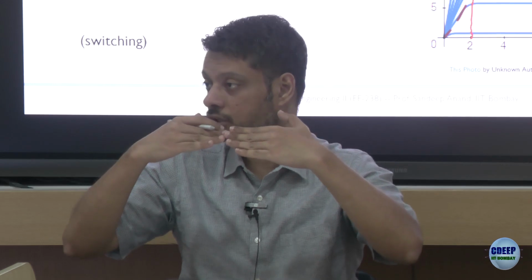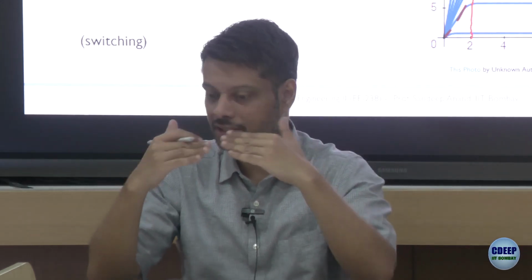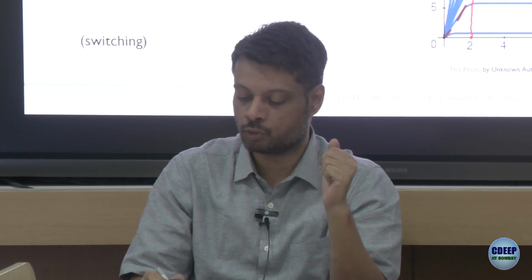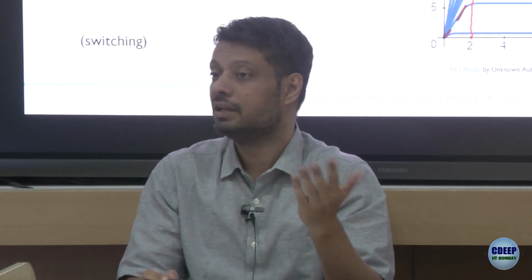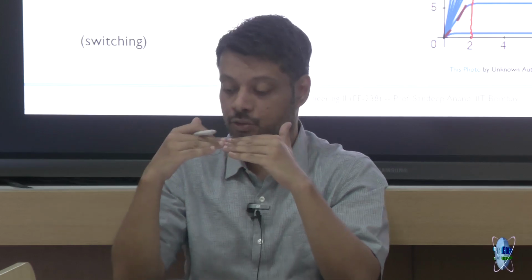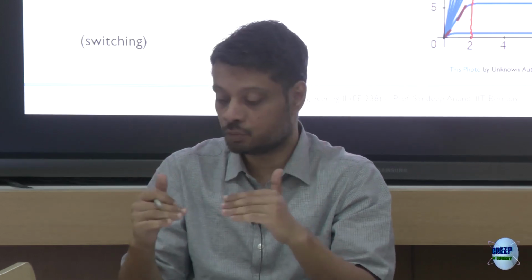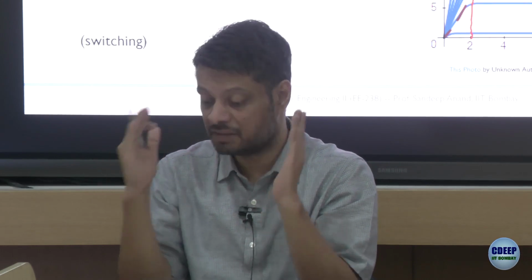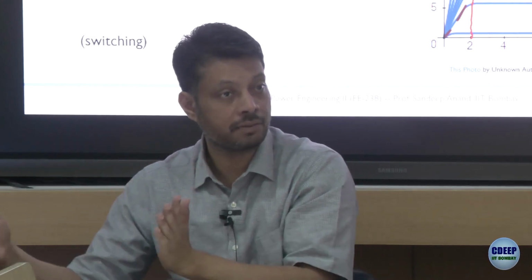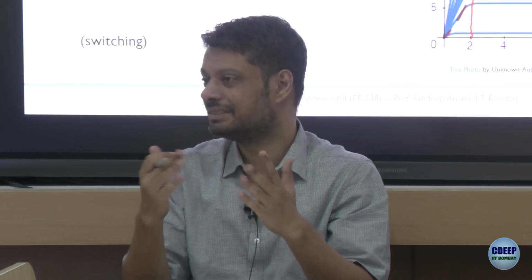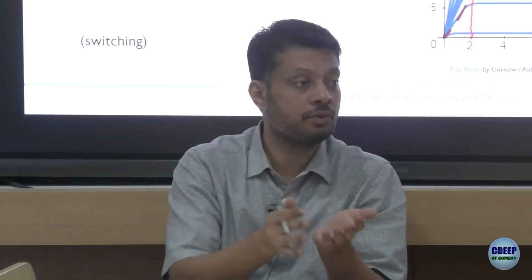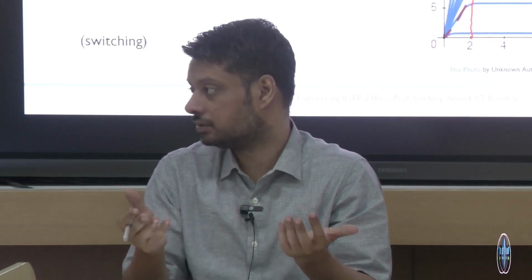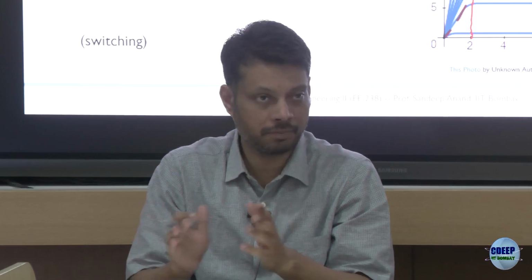It acts as a short circuit, not a perfect one, but a very good short circuit, because the voltage drop is only 2 volt even while pushing a very large current of 25 ampere. When I want to open it, I give a gate to source voltage of 0 volt, and it will not allow any current to flow, even if you apply 14 volt, even 100 volt. So this feels like a switch you could have used in the previous circuit. Plus, because it's a semiconductor switch, it can switch much faster, in kilohertz, no problem.